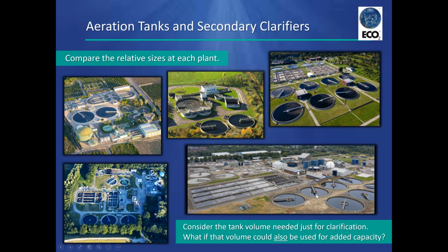So we look at that system and we say, the clarifier, great big tank, is sitting there doing one thing, and that is settling out the mixed liquor. So the next question we would ask is, relatively speaking, how much of the biomass is sitting in the sludge blanket in this clarifier compared to the amount of biomass in that aeration tank?